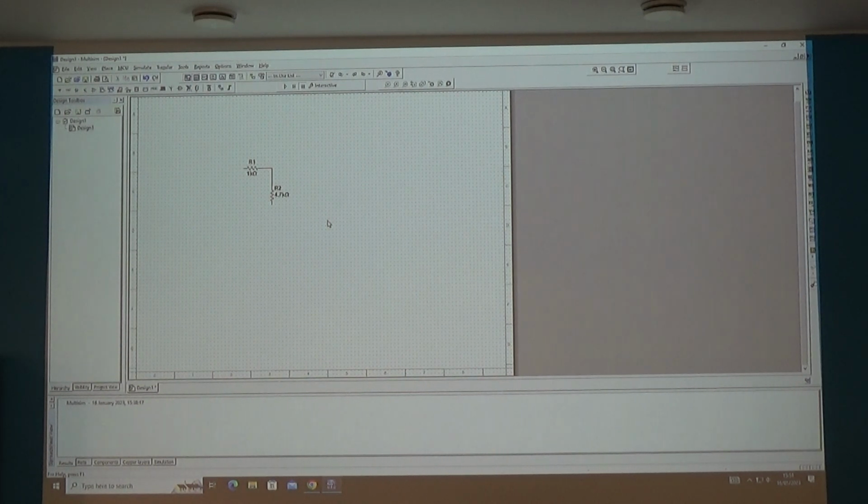And that's one of the commonest faults that you'll come across, people aren't joining the components together, and it's really difficult to see in a simulation when that connection is broken. Okay, make sure you can do that. Join 2 components together. Doesn't matter which components, join them. You should have a red wire when you finish, indicating that the connection is complete. Yeah? Everyone good to go on that? Absolutely vital skill, that one. Get the components in, get the components connected.